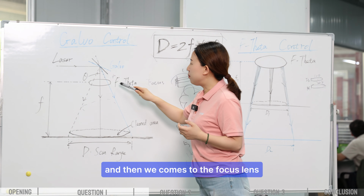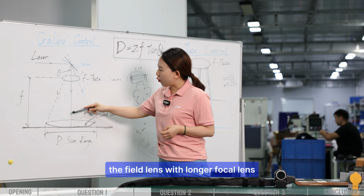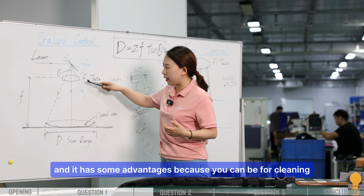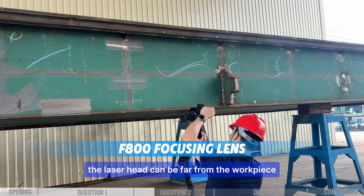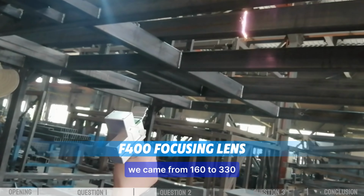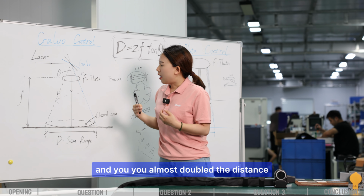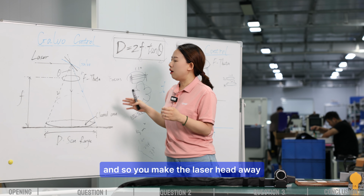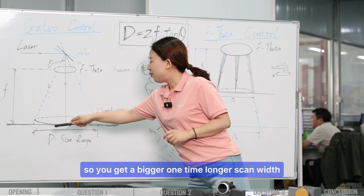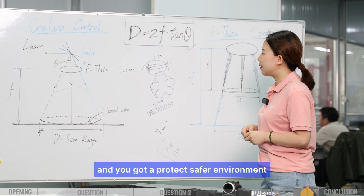And then we come to the focal length. A longer focal length has some advantages, because for cleaning, the laser head can be far from the workpiece. The focal length comes from 160 to 330, and you almost double the distance, so you make the laser head farther away from the dust. You get a bigger, longer scan width, and you get a safer environment.